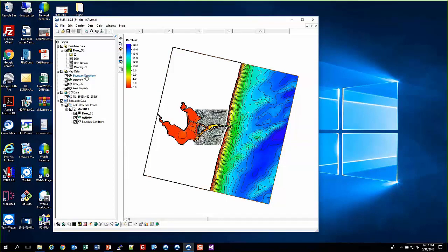So just to go over a couple of the things, I'm going to show how to do the annotations. So we will come down to the annotations module. We'll enable that. We have our options here. I will choose to do a north arrow and just mark out a box where I want to put it.